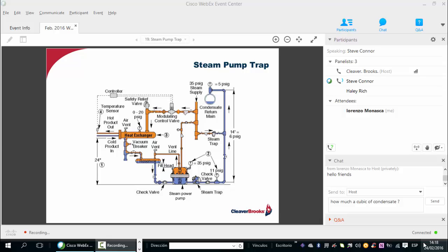Now, as you can see, with this arrangement, steam and condensate are present in the steam pump, and as the condensate collects within it, the float rises and allows this pump to evacuate the fluid, and then steam re-enters as the condensate is evacuated.